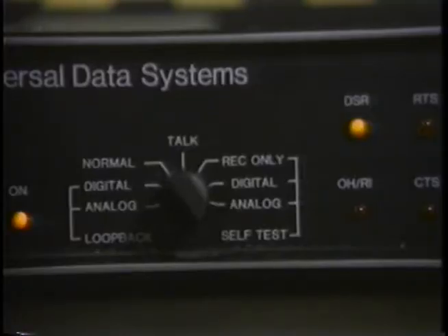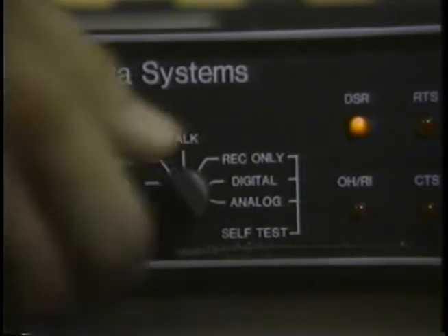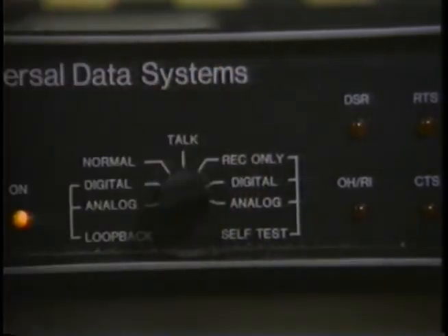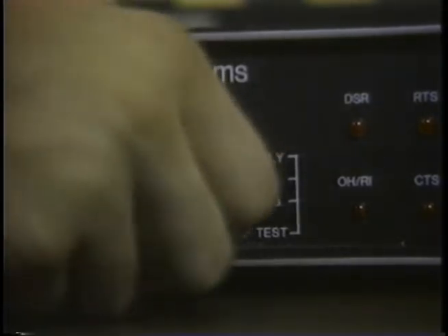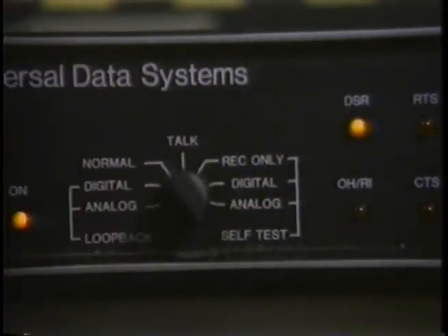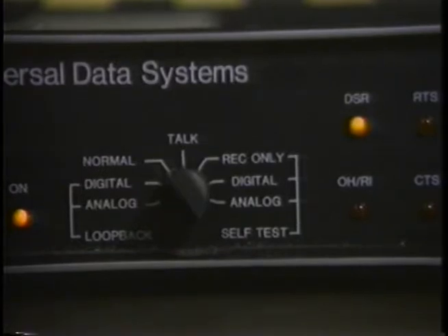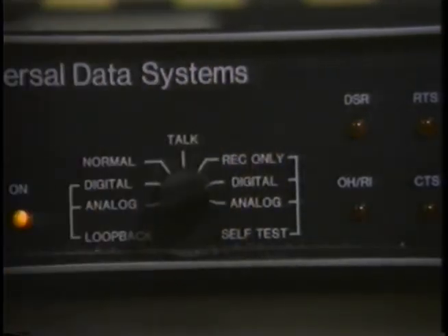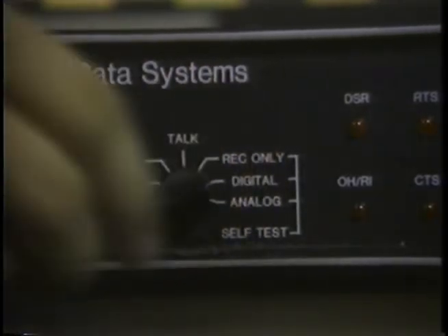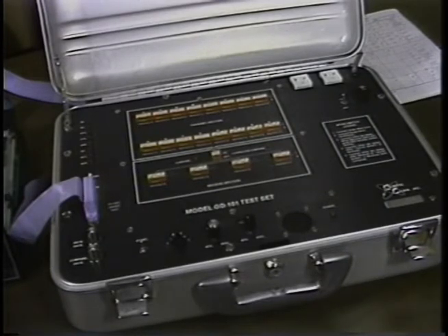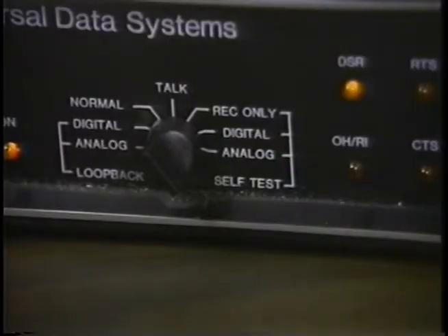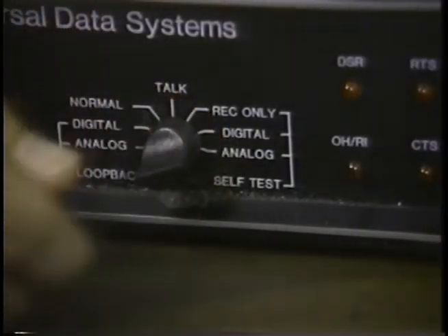The rationale for turning DSR off is that the data set is not ready to transmit normal data during testing and is telling the terminal or computer not to assume normal operation until DSR is on. The reason for sometimes having DSR on during testing is that some test equipment may require the signal to be on before sending test data. The most typical setting is to have DSR off during loopback test.